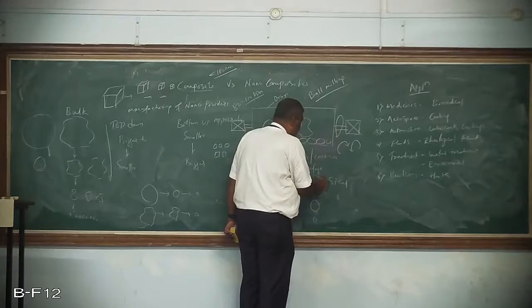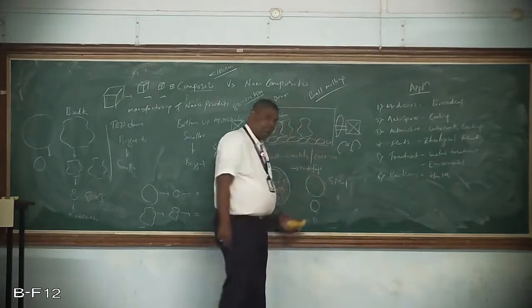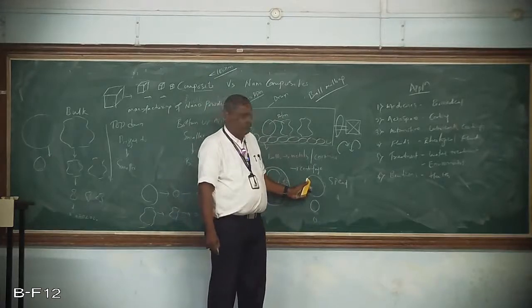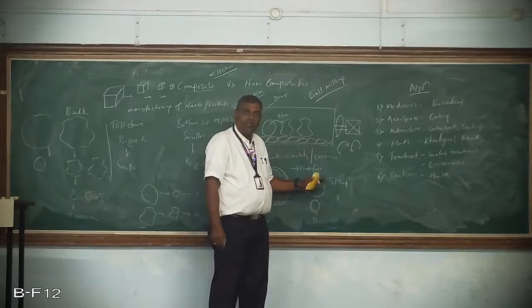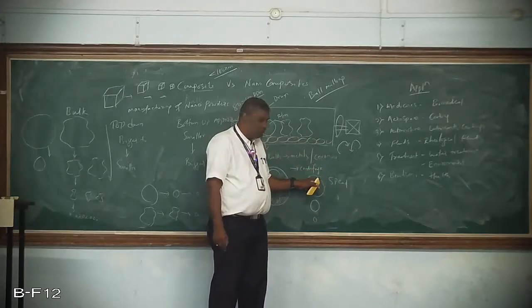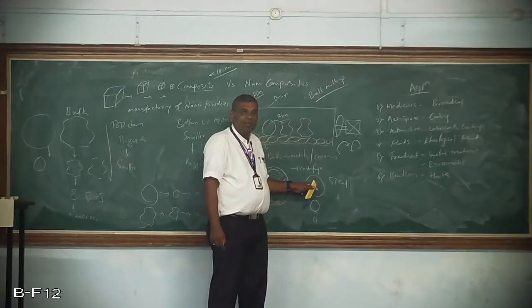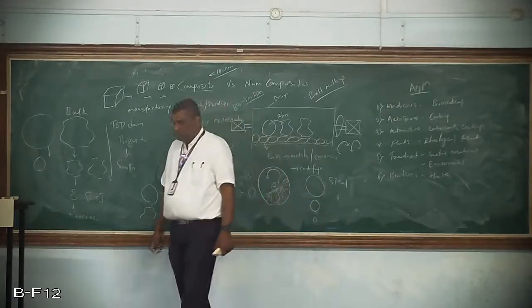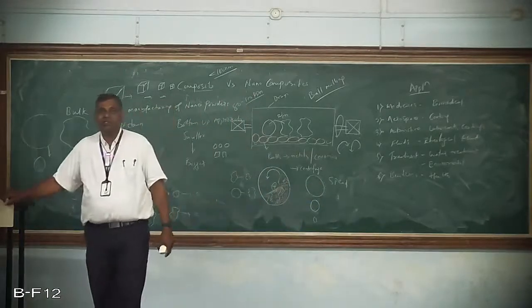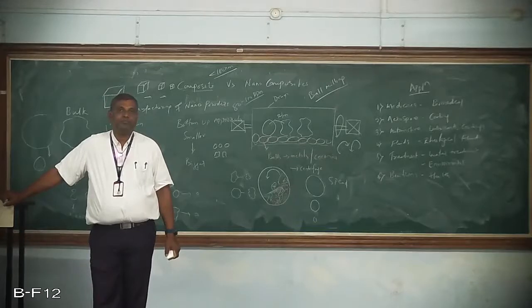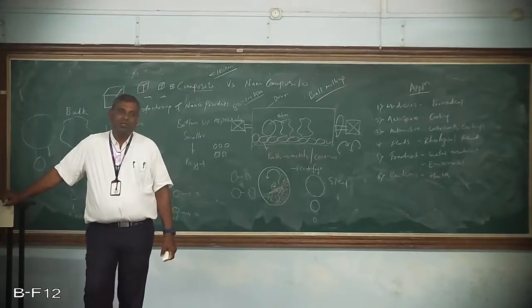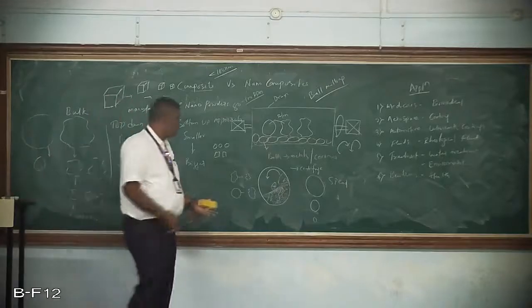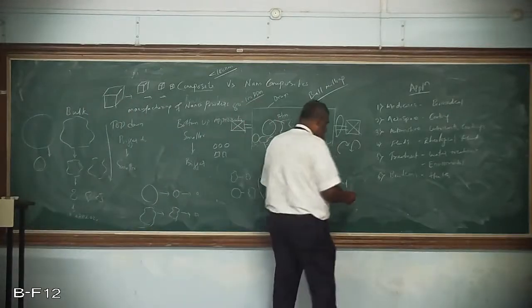Then it becomes a micro weld. The raw material adheres on the surface of the ball, so this gets welded and you cannot separate it out. Over a period of time, this raw material will become an integral part of your balls. Hence it reduces the efficiency of the impact. All these are the drawbacks. The agglomeration or deposition of the bulk material will happen on the balls.